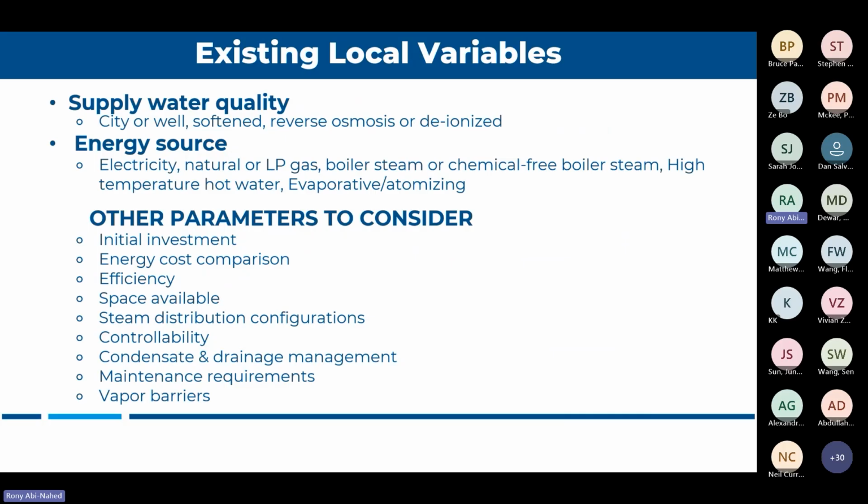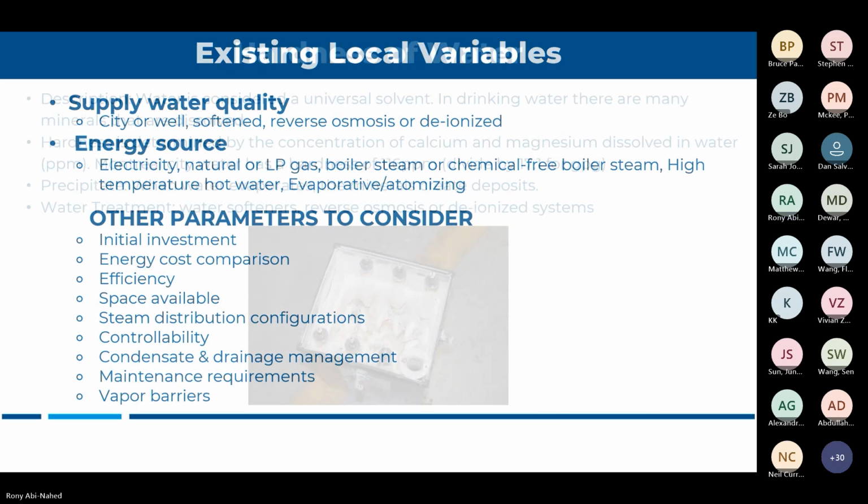Now, one point that a lot of customers don't know the answer to, but it's really important, is the water quality you're dealing with. Depending on where you're installing the job, in some cities or areas the tap water is fine. In other areas, they have very hard water. Hard water means there's a lot of calcium and magnesium in the water, and we need to know that because it will have a big effect on how the unit will operate.